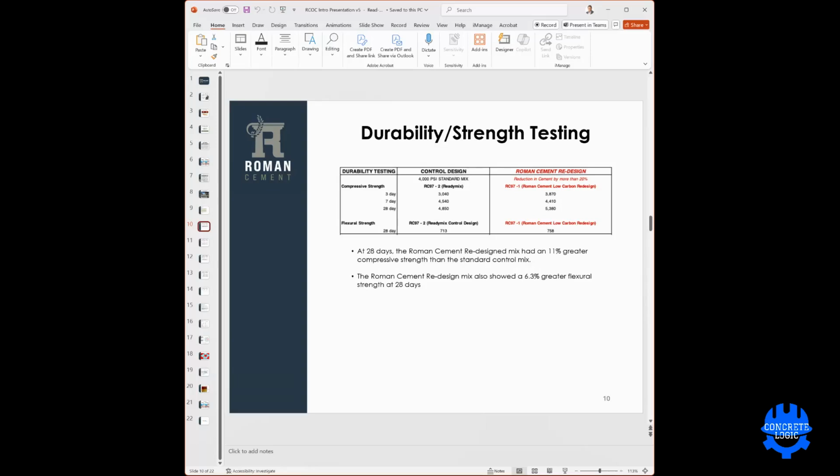So I can envision the natural pozzolan that's being produced in Utah being blended with a limestone powder without grinding, so you can get the right particle size ranges. And then they could sell that as a blended product. And maybe by selling the cement in tandem with this blended product, the cement companies might get credit for having produced a low carbon cement anyway. So that's just an idea.